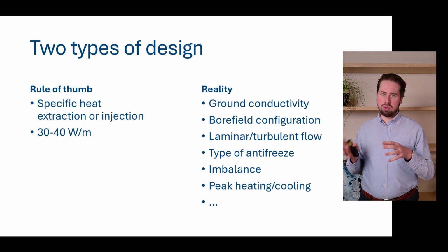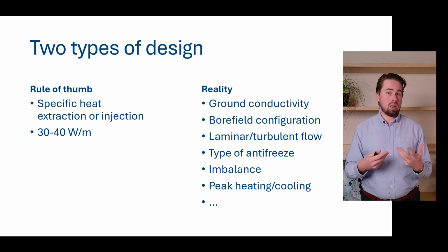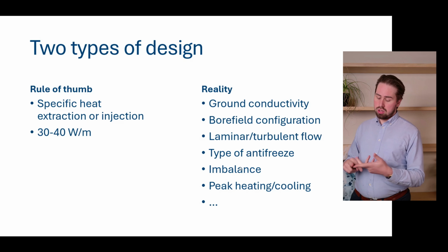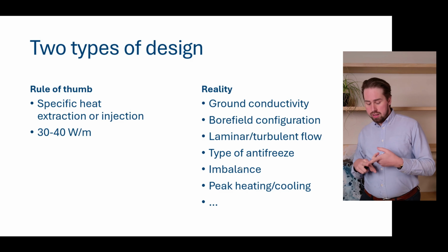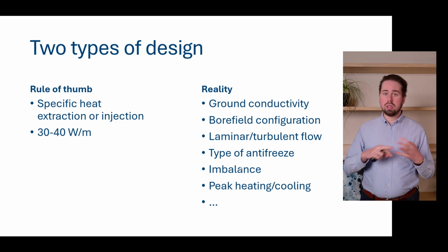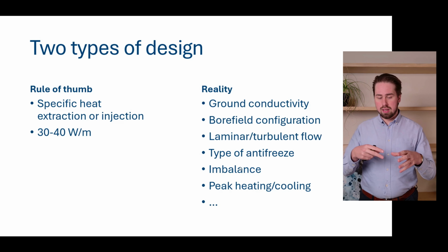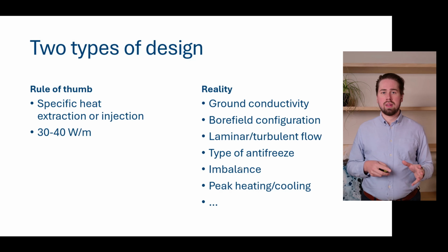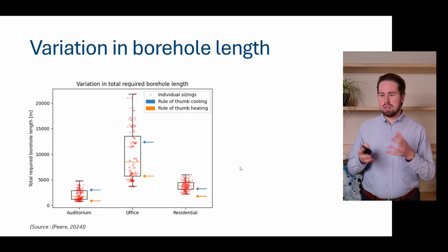And what we then did is, for each of these 3 buildings, we varied all the input parameters you will encounter in your daily borefield design life. Namely, we have a good conducting soil or a bad conducting soil. We are going to drill deeper or shallower. We're going to use active cooling or passive cooling. We're going to use water or antifreeze, and so forth and so forth. So we end up with quite a lot of variations, and for each of these real situations, we determined the required borefield size, and we put that next to the design we would have when we just simply used 30 watts per meter. And the results are seen here.